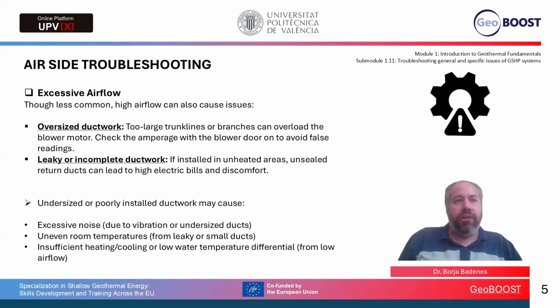But also, too much airflow causes issues too. For example, oversized ducts, large trunk or branches can overload the blower. Leaky ducts, unsealed return ducts in unheated spaces waste energy and comfort. And finally, a poor installation. Badly sized or badly styled ducts cause noise, uneven temperature, or low water side temperature difference. Always measure blower amperage and inspect the duct sealing.